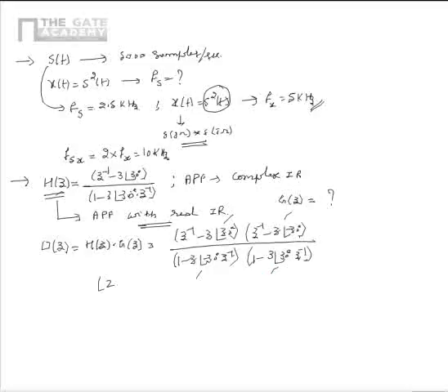Also please note that zeros and poles will form a conjugate reciprocal pair, because of which the overall system function would be all pass. So the system that needs to be connected in cascade is G(z), which is highlighted as shown.